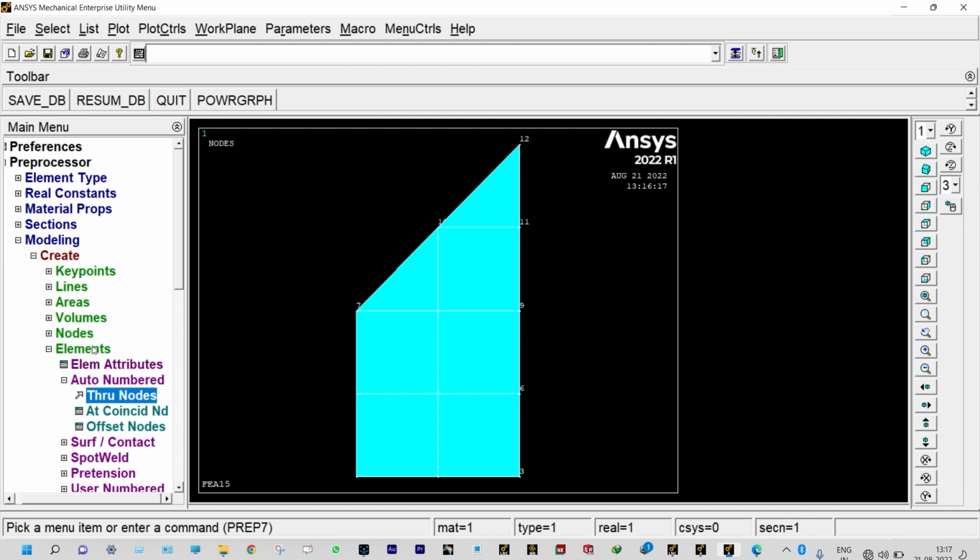Okay, we made these whole elements and it is comprising the 1/8 of the whole segment. The areas are actually symmetric, so whatever result will be obtained in this area, that will be symmetric for other cases also. It is actually a simpler meshing method. In this way we are making a structured mesh, right? And our meshing is complete.